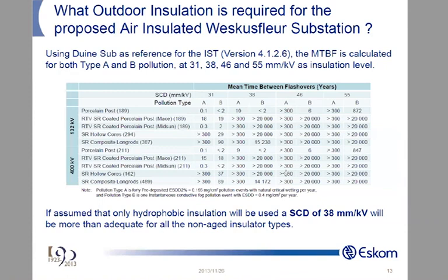And as they migrate into the pollution layer, is this bottom part in the layer dissolvable? No. But the area at the top is becoming smaller, smaller, smaller because they're migrating up. So what's happening to the area A? Becoming smaller, smaller, smaller. R goes up, up, up. The resistivity of that whole layer goes up, up, up. R goes up, up, up. I becomes small. Your risk of flashover is far lower. You got it? Cool. You've been empowered.